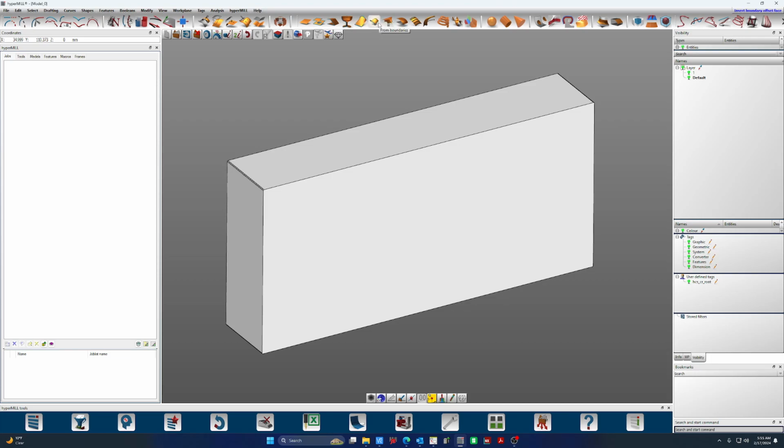From boundaries I use as well. From boundaries is similar to ruled, but ruled has some rules because it's designed to create a surface that has, I believe, a little bit more strict isoparametrics. Between boundaries will give you different results, and you can create some quite bizarre shapes that don't follow the same rules. As does filling. Filling is like the final step in the bizarre surface creation.